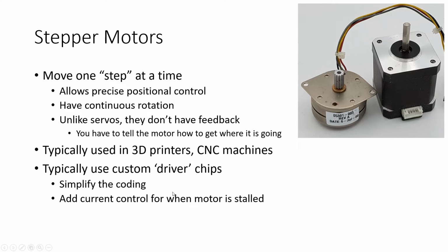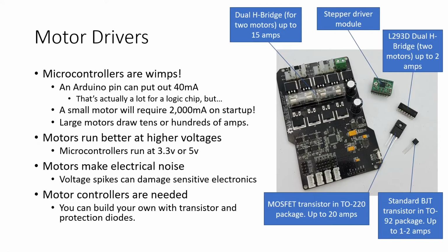For our stepper motors, you'll typically use a custom driver chip. You can drive them directly from a microcontroller using standard motor drivers or amplification or even transistors to build your own stepper motor controller. But there are some more advanced chips that allow you to do things like current control so that you don't overheat your motors and waste power when they are stopped.